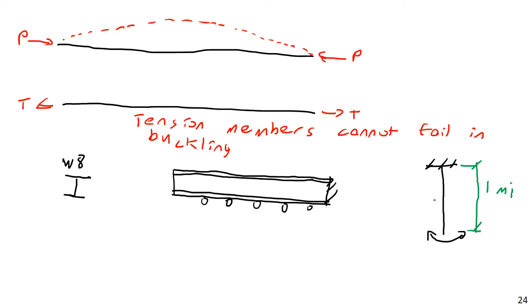Well, the flexibility of something, as you learn from mechanics of materials, bending or displacement is going to depend not only on the moment of inertia, but the length. And it tends to increase with the third or the fourth power of length, that kind of thing. So if you have this set up with a really incredibly long length, and you take that length to the third or fourth power, oh boy, that's going to be pretty crazy. And I think that should be a third power, I believe, with a point load. Anyway, so this thing's just going to wobble back and forth.